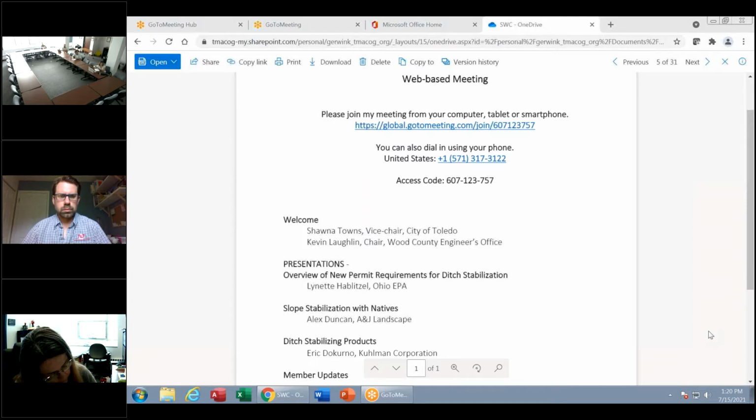Okay, thanks, Lynette. And then a question from Mike Moulton. Are commercial developers responsible for acquiring their own permits? Yes. So if we have a commercial development, say a subdivision, and they're going to create a ditch or realign a ditch, then they are obligated to get their NPDES permit coverage if they're going to hit that earth disturbance of 1 acre or more. I hope that answers your question.